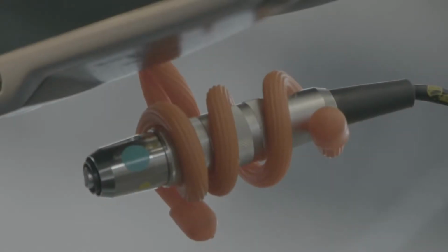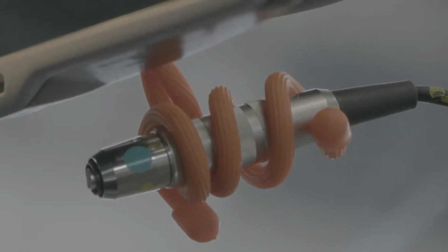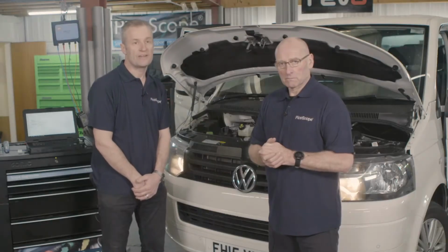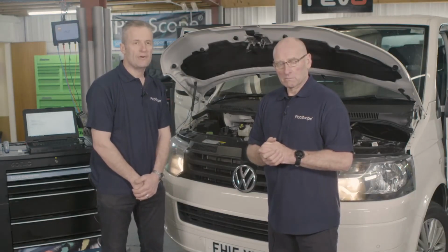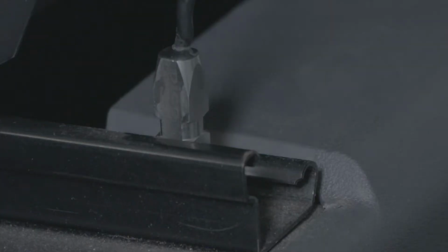So what we've done here with the van is simulated exactly what you saw in the animation. We've introduced a deliberate imbalance to the cooling fan. We've also introduced the microphone into the cabin. So not only will we measure the vibration, but we'll measure the sound, which, remember, is one and the same thing. The microphone and the accelerometer both detect the vibration, the sound generated, and display them differently, but at the same frequency.